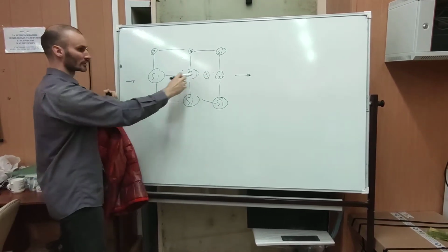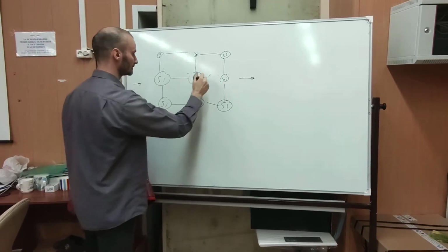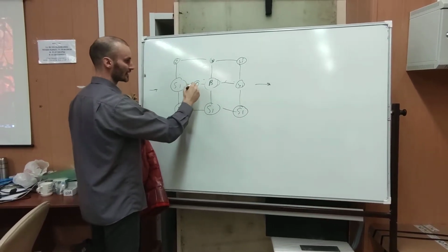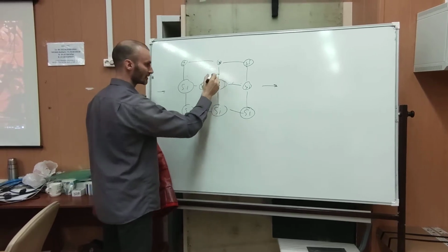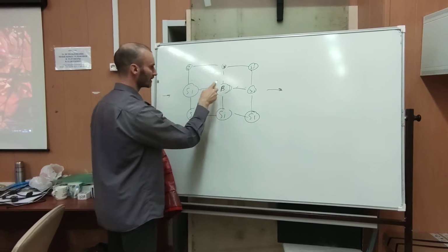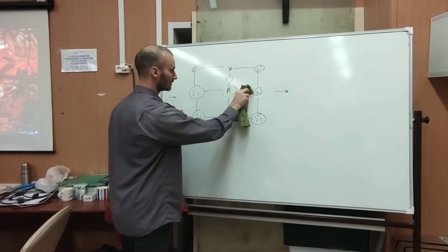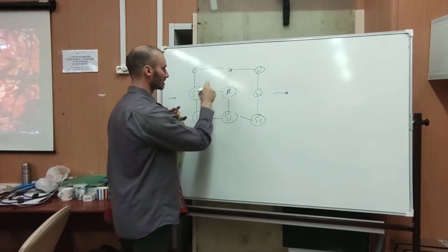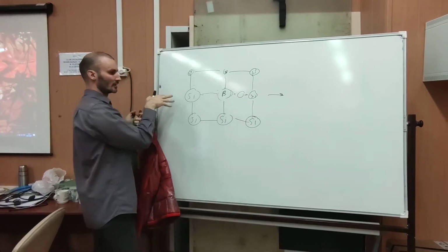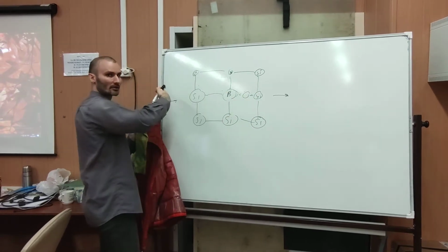So as you apply voltage in this direction, the hole, let's draw it on the other side, the hole which is here starts jumping around. So it jumps here. So what happens is you now have a link here and a hole here. Then it jumps this way. So you have a link here and a hole here, and so on. So the hole jumps in this direction. That actually means that all other electrons move in the opposite direction.